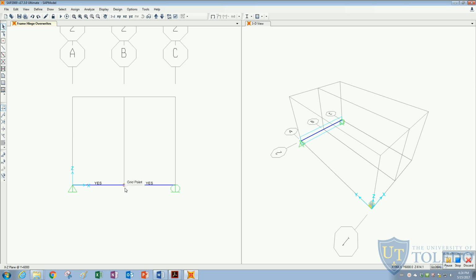Since I calculated that it should resist about 430 kilonewtons, I'm going to apply 2 times this load to this beam, because that way I'm absolutely sure this beam should fail. If it doesn't fail with that load, there's something wrong. Doing hand calculations is also a good idea because it will give you a sense if your model is wrong or right. If I calculated 430 and I get 1,000 capacity from this beam, there's something wrong.